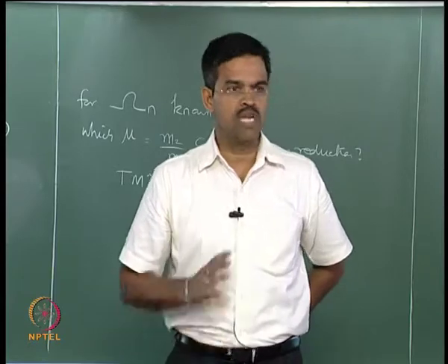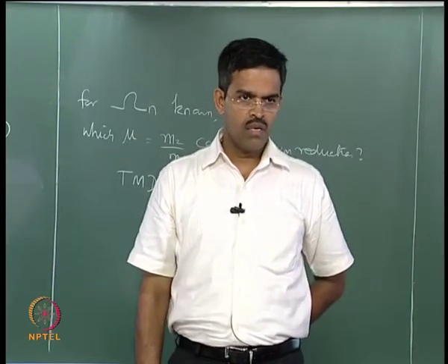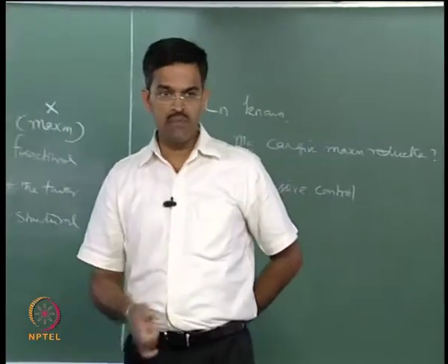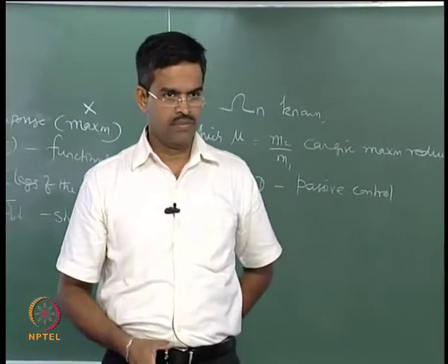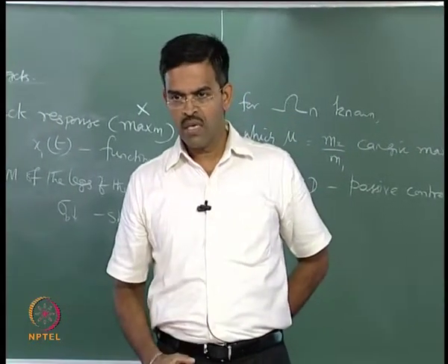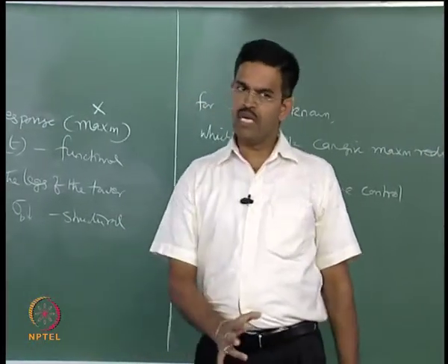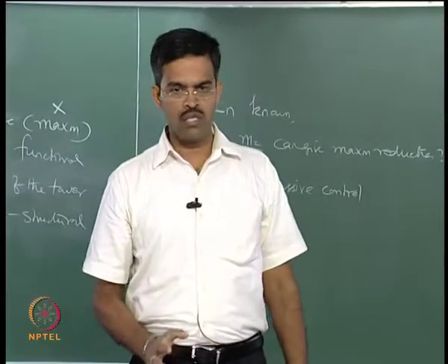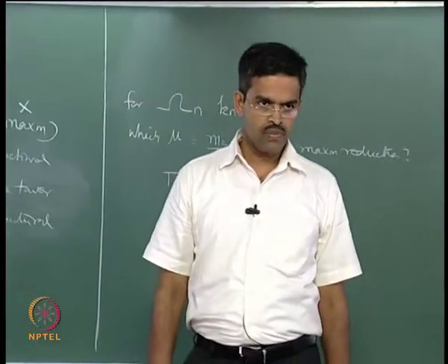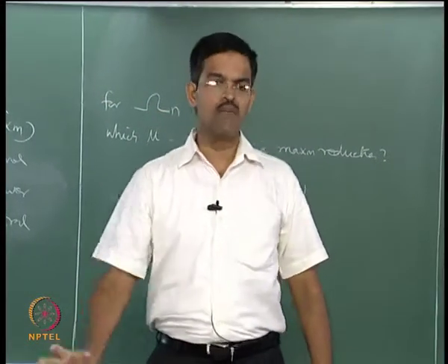So, you are not able to shift that. What you are seeing is reduction in magnitude only. Okay, that is important. It means TMD provision or secondary mass provision in the system qualitatively is not altering the structural behavior, in terms of bending moment.